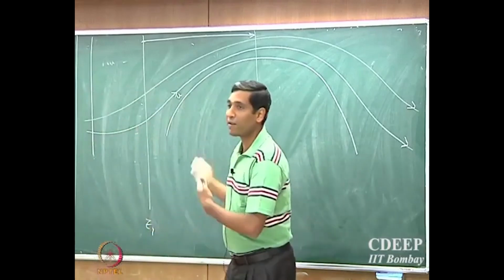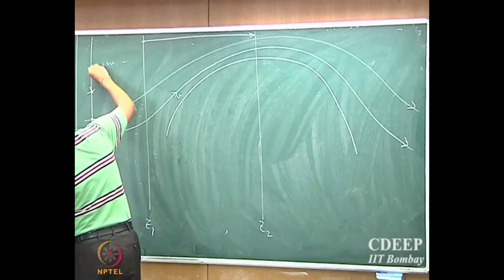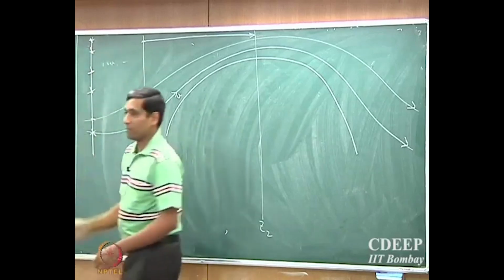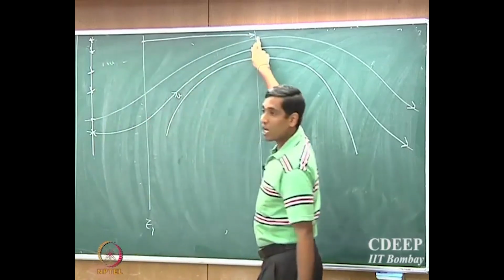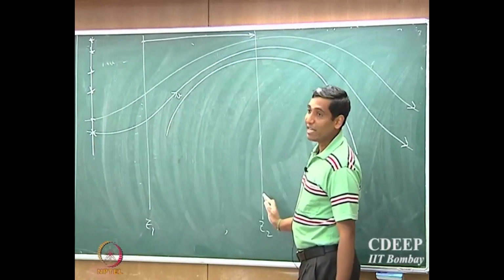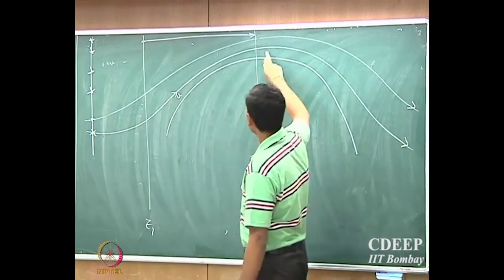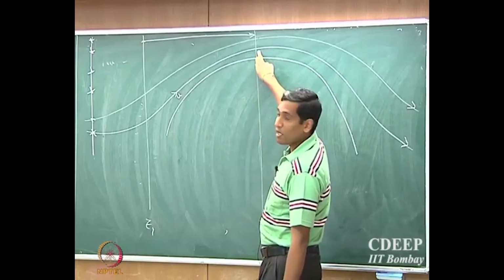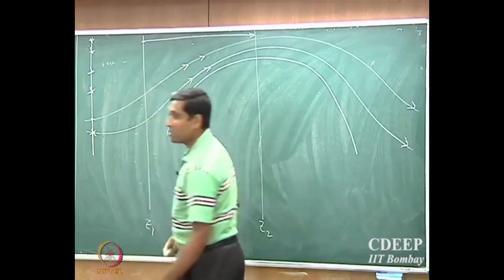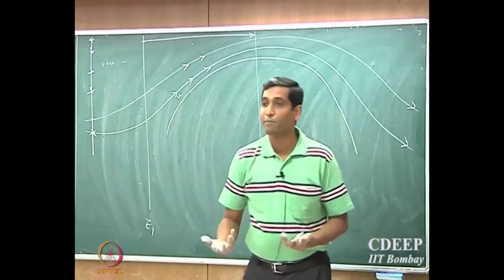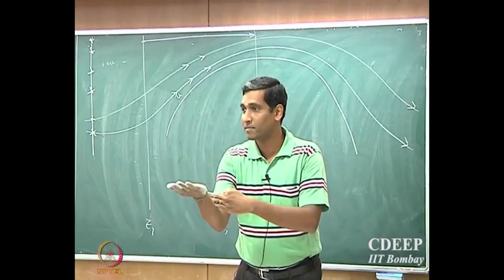So, if you look at very far away upstream, all of these particles would have actually started at the same time. So, the distance that the fluid stream well above covers in order to reach the same plane is much smaller than what these fluid particles have to cover to reach this location. So, therefore, the fluid particles which are close to the cylinder, or which are experiencing the presence of the cylinder, have to accelerate in order to catch up.